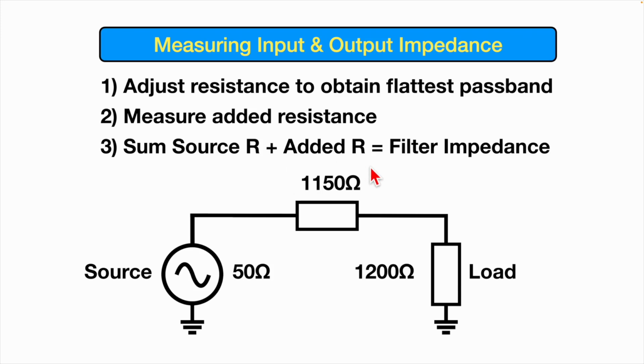And when I say two impedances, I mean this one and this one counts as one, and this counts as the other. Now we know this portion of this impedance because it's the NanoVNA, it's 50 ohms. But once we've measured this one, then we know what the total is here, and we know that this total matches this. So although we didn't know what this one was, we do now, right? Because we add these two together, and this is the simple voltage divider method. And it works pretty well. And major respect to Charlie Morris, ZL2CTM. He's the one that I picked this up from first of all. And I've used this on all my crystal filters, and it seems to work really well.